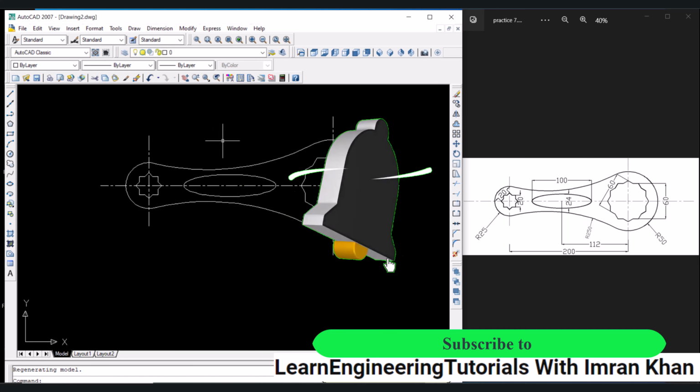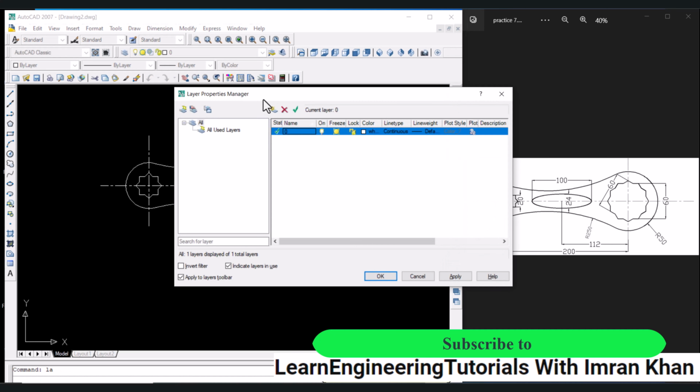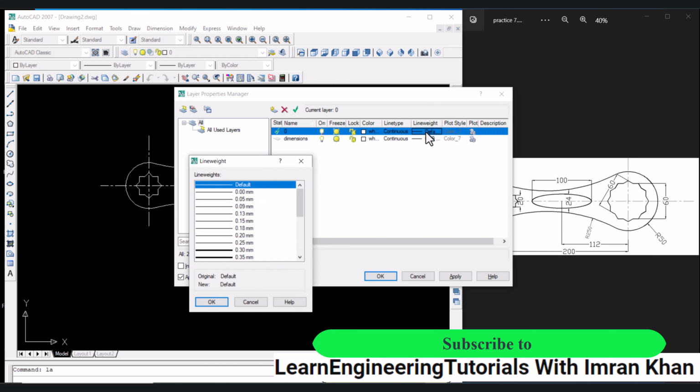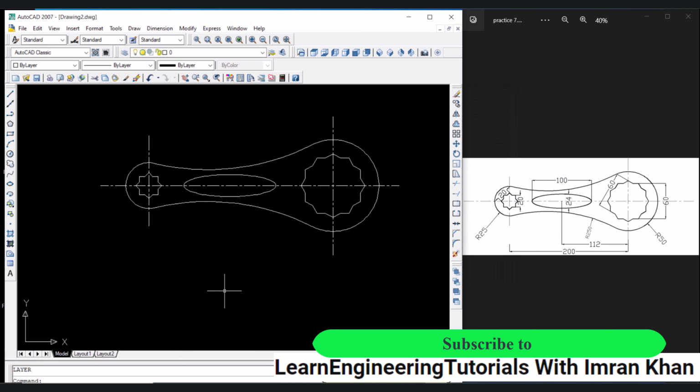For that, let us add a layer, so LA, enter, add a new layer, rename the layer to be dimensions, click on the line type, let it be a thin line, and let the default or solid lines be thick lines. So click on 0.5, click on OK, click on OK.